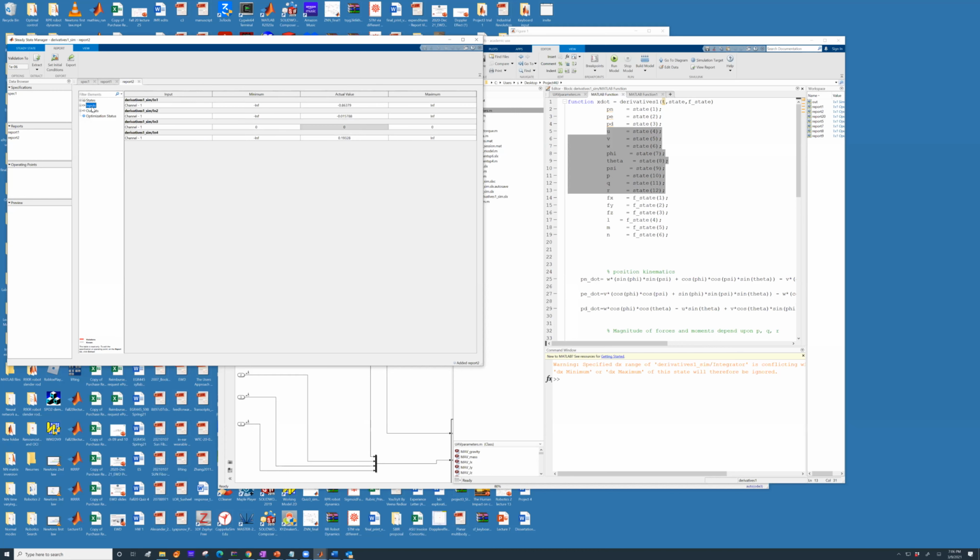Let's look at the input. Please note, rudder is staying at 0, which means it's not using rudder. But I want you to observe that the trim value for the elevator and the aileron and the thrust are now different. The channel value for the elevator has changed.